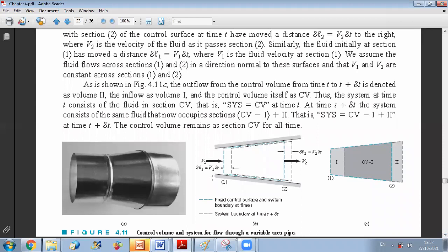In this 2D example we have a nozzle, and as we said before, we need to try to relate properties of a system and the control volume. So let's say you have a flow through this nozzle, and you want to characterize the flow behavior. Now you will say, I am interested in the flow field within my nozzle. So my control volume will be the nozzle, let's say. Now my system will be some particles that at a certain instant were inside the nozzle, but if I want to follow them with time, they will not always remain inside it.